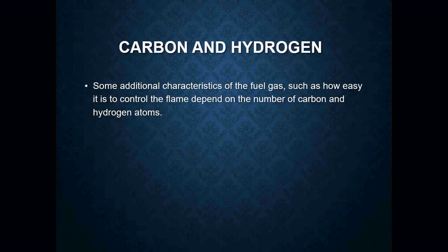My gas orifices are just metering devices. They regulate a certain amount of gas to each one of my burners. If those are not correct, I'm either introducing too much gas or too little, and that can honestly create a problem.